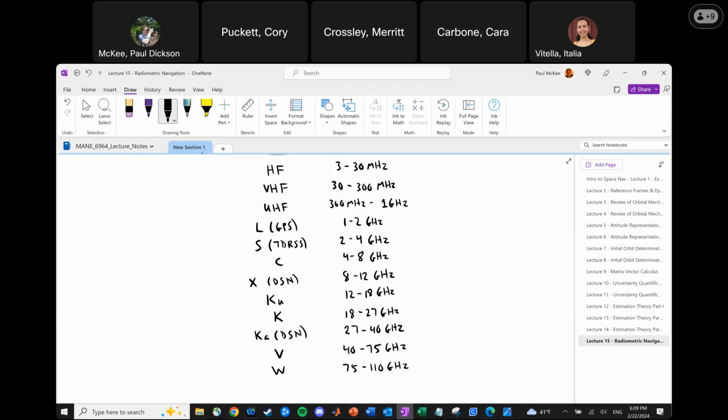Or I was in a meeting one time asking about how we do relative navigation between Artemis or the Orion vehicle and whatever it's docking to, whether that's HLS or Gateway or what have you. And somebody, in a not rude but kind of dismissive way, was just like, oh, we just use S-band comm for range. And I knew what that meant because I had taken this class and seen this chart. So it uses S-band communication. You can get your two-way range from that using some of the techniques that we'll talk about today.